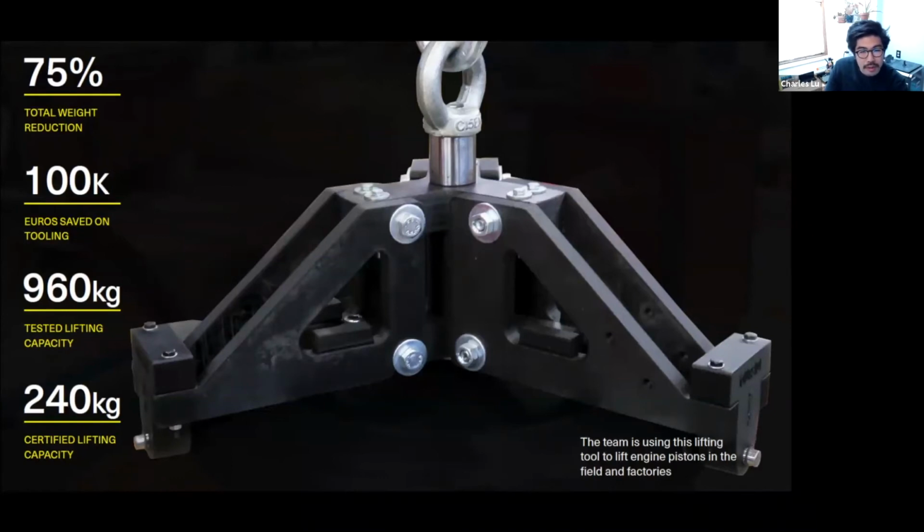Why is the Onyx ESD tensile strength higher than the regular Onyx? It contains a different type of carbon. Because it is conductive, we're adding a conductive additive. That additive actually imparts more stiffness at the cost of some amount of durability. It also has a different polymer matrix, so there's a little bit of difference there.